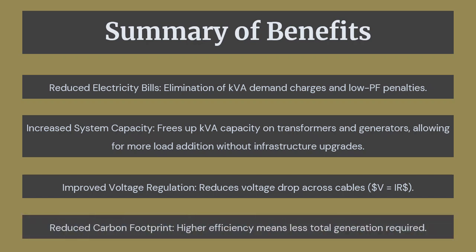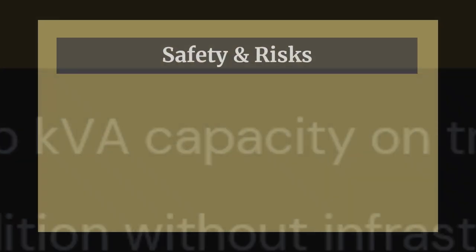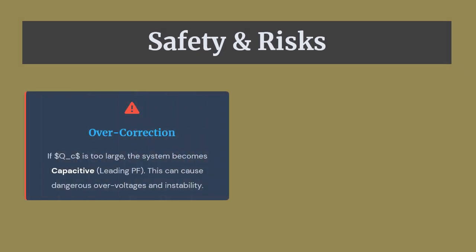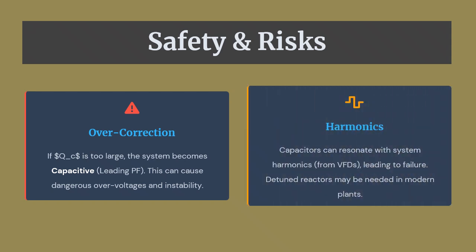Safety and risks. A final word of caution. Do not overcorrect. If your capacitor bank is too large, your power factor becomes leading or capacitive, which can cause dangerous overvoltages. Also, be aware of harmonics. If your facility uses variable frequency drives, VFDs, standard capacitors can resonate and fail. In those cases, detuned reactors are required.